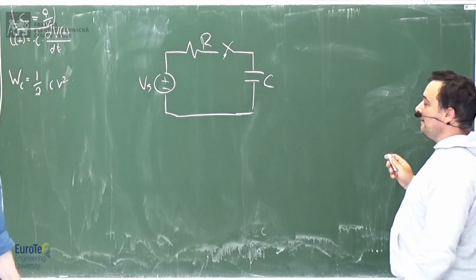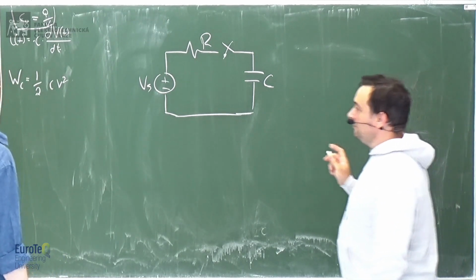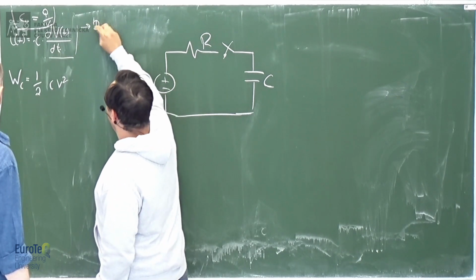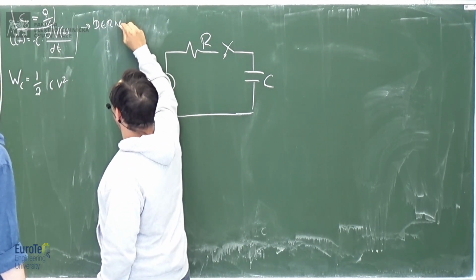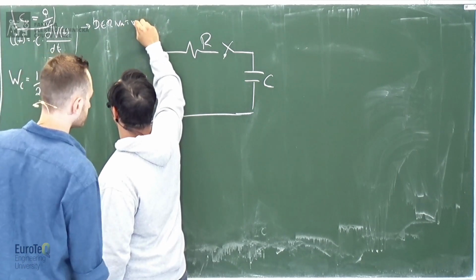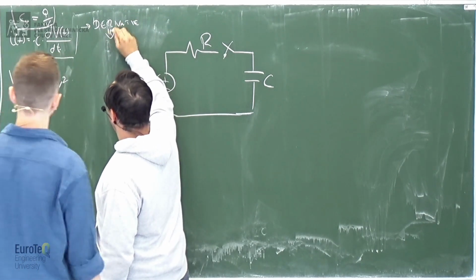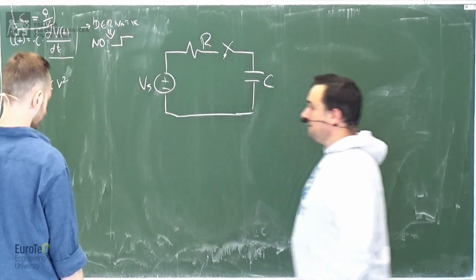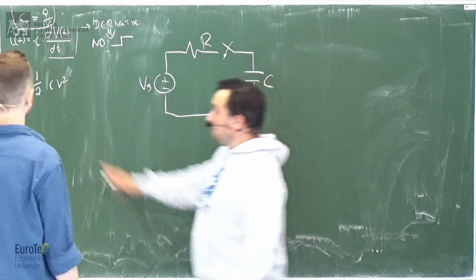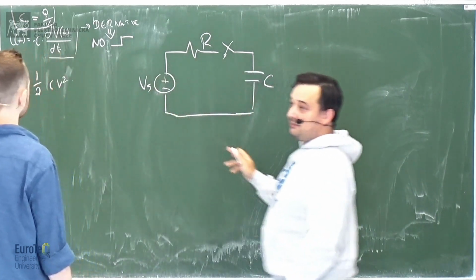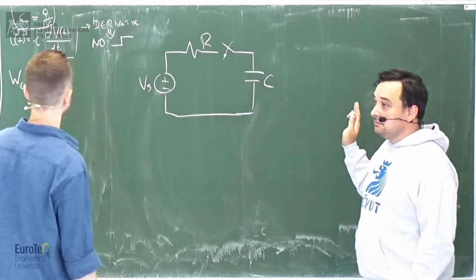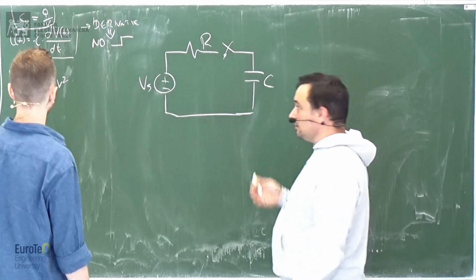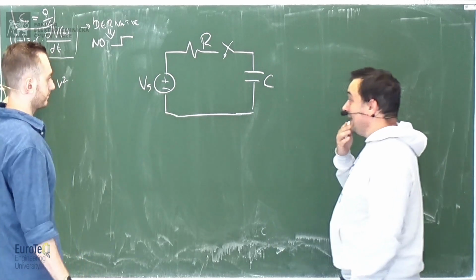Now, one thing to remember, so always watch where there is the derivative. When you have the derivative, it means that it cannot have a step. So the voltage is not going to have a step response. The current, no problem whatsoever. It can change instantaneously, but it will be limited by these.